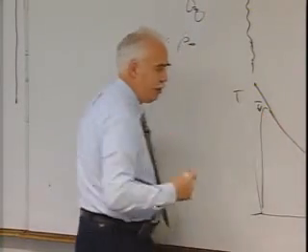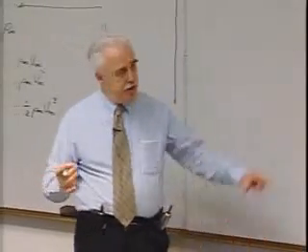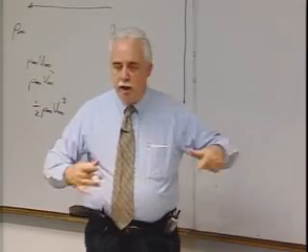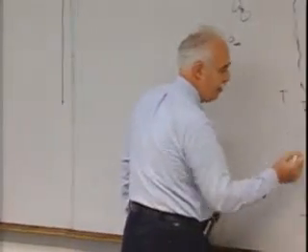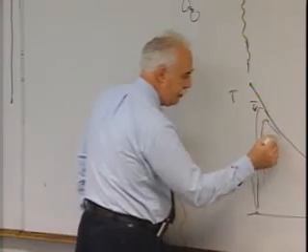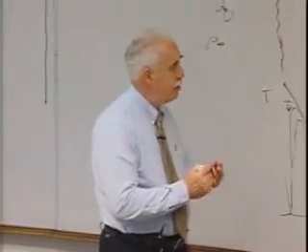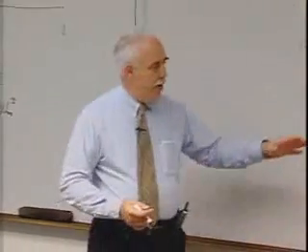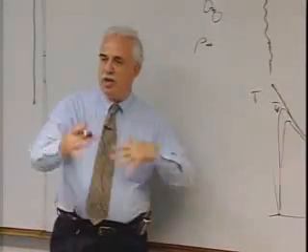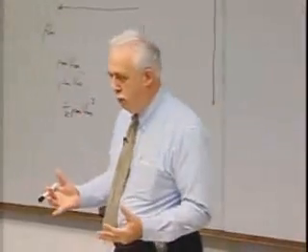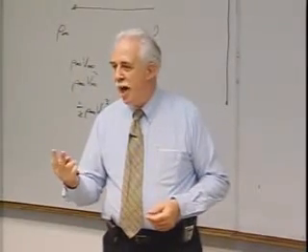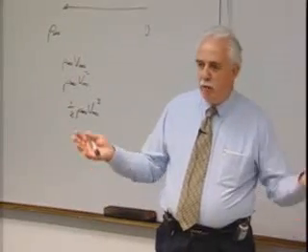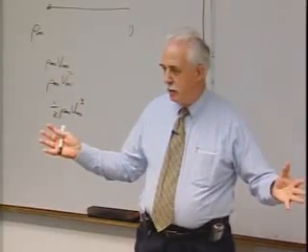A vibrational temperature, again, the temperature doesn't really have, this is a very non-equilibrium situation. So the concept of temperature really goes away, but it's sort of a measure of energy to equate, for example, vibrational and electronic. Now what happened was I mentioned how significant the radiation was from the equilibrium. In the shock tube, the radiation in this region, where the energy has not distributed itself into an equilibrium level, was 2 orders of magnitude higher. That led to the publication, you can't bring people back from the moon. That radiation is just going to vaporize the capsule.